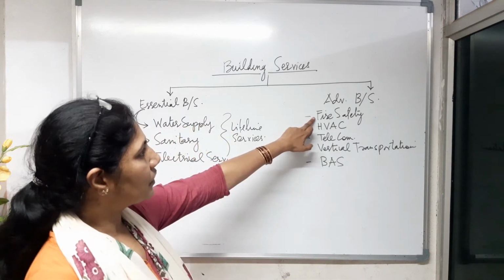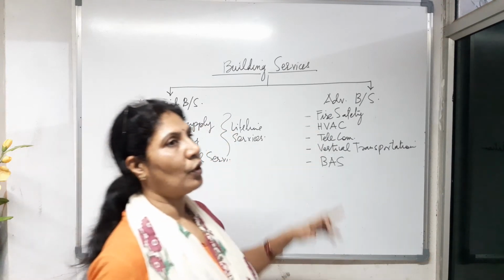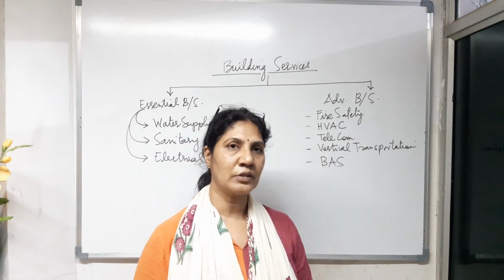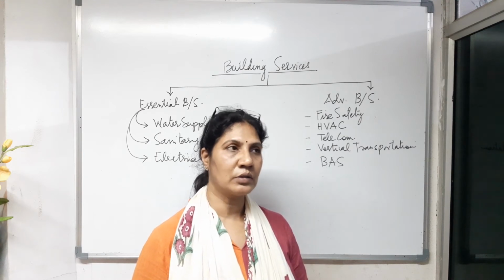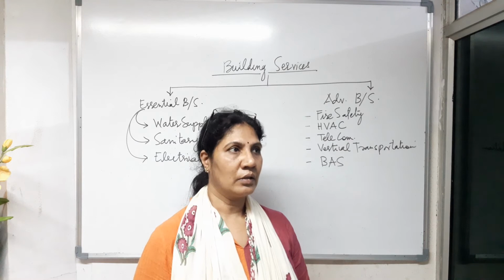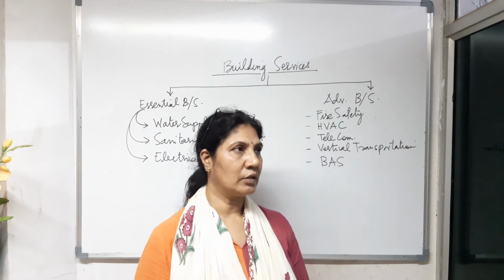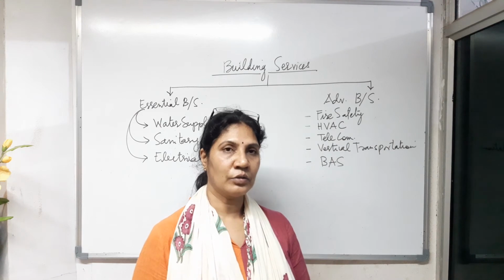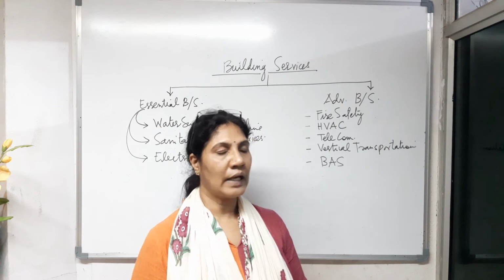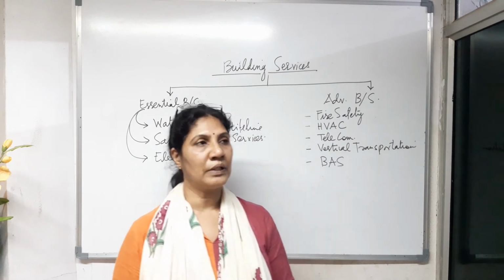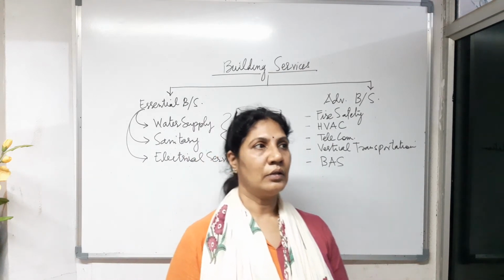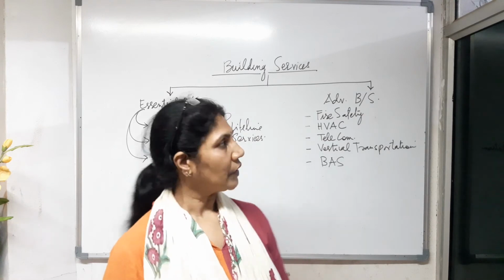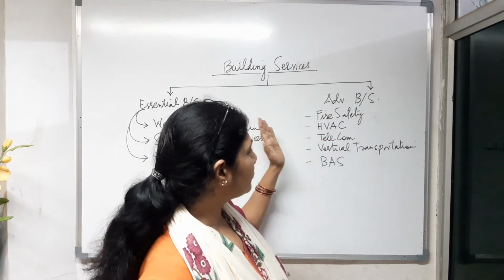So fire safety services basically deal with provision of the active and passive fire safety systems in buildings, like planning for escape routes and fire walls, fire escape staircase, and various other selection of building materials to make any building fire resistant, and of course the active systems like sprinkler systems, provision of various fire extinguishers, and how to plan all these things. All that is covered under fire safety systems.